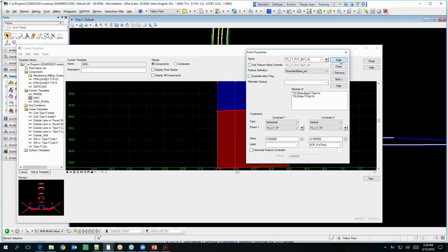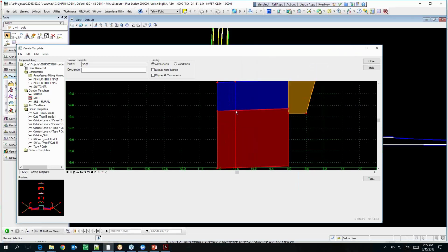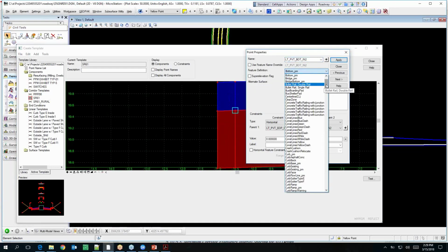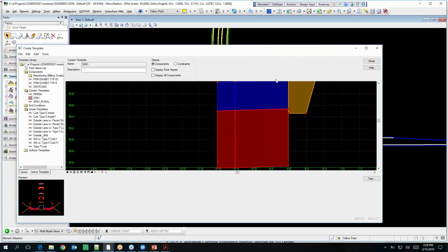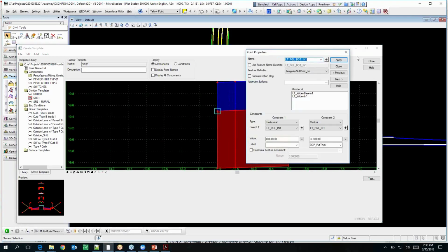This is one of those areas, actually, that I would say Civil 3D is probably a little easier to do. You can generate a bottom surface in like two clicks, by corridor. You can do that very easily by going to the stages and going from final to bottom surface. Done. But when you're trying to do it for the whole contiguous corridor, we have 1, 2, 3, 4 plus a surface template. There's a lot of pieces to the puzzle here.